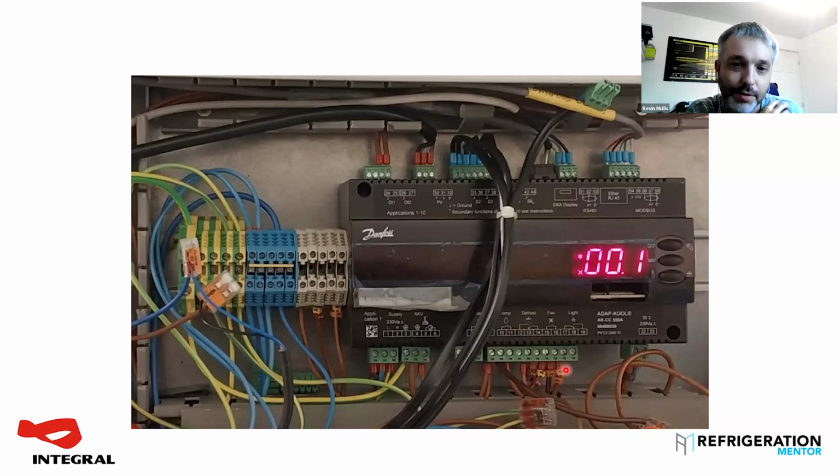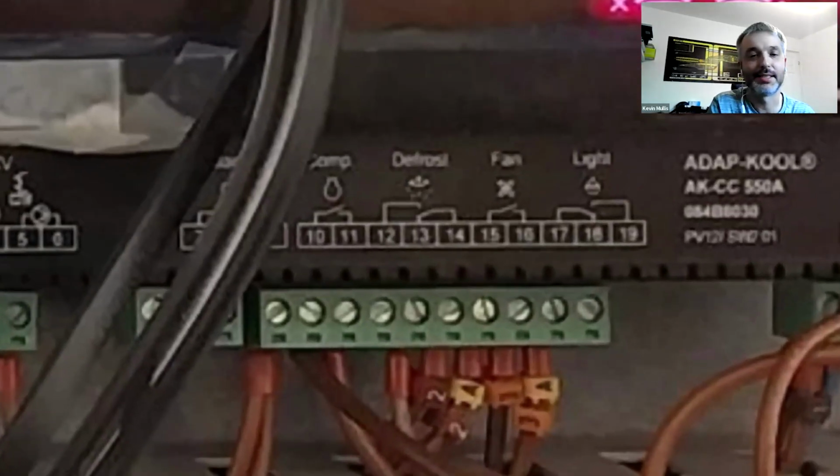So, if you've got no fans, for example, all these relays are just voltage in one side and then the switch feed out of the other side. So that's going to be your first point. If you've got no fans, the controller's got the fan symbol on, as you can see there, is there actually any voltage coming out through the relay? And is that relay running the fans directly? Is it going to a contactor in the tray or something like that? But check there, make sure.